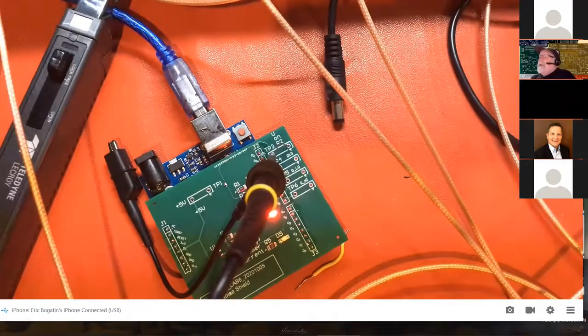And the second is, when we're looking at a signal, in this case in the time domain, if we wanted to look in the frequency domain, having a higher bit resolution means our digitizing noise floor is lower with 12-bit than if we had 8-bit. And that gives us a little bit better dynamic range when we look in the frequency domain. When you look at emissions, both domains, time domain and frequency domain, are equally important. Everything is about opening up a window into what's going on in your system.